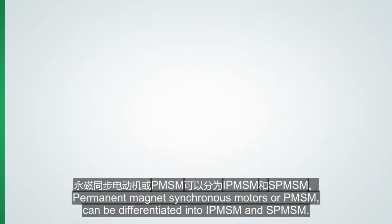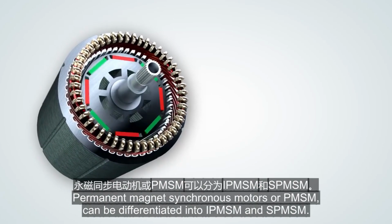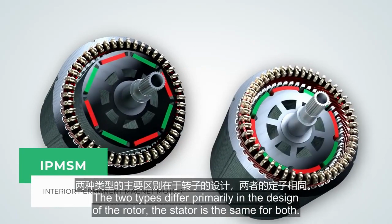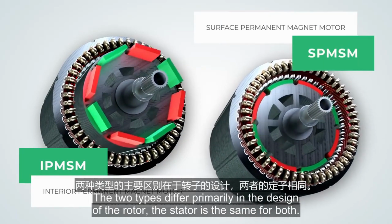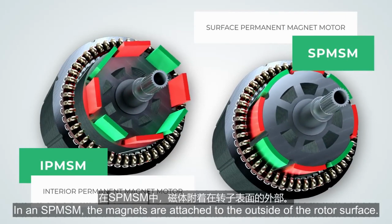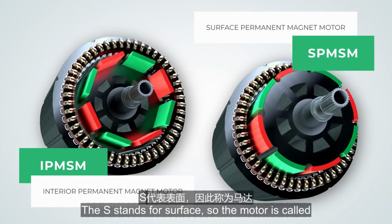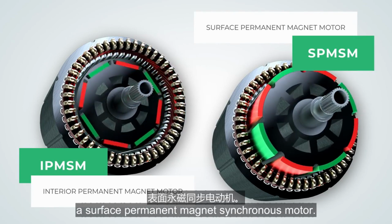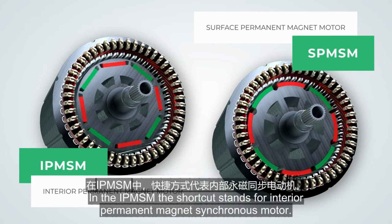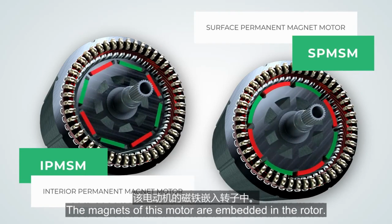Permanent magnet synchronous motors, or PMSM, can be differentiated into IPMSM and SPMSM. The two types differ primarily in the design of the rotor. The stator is the same for both. In an SPMSM, the magnets are attached to the outside of the rotor surface. The S stands for surface, so the motor is called a surface permanent magnet synchronous motor. In an IPMSM, the shortcut stands for interior permanent magnet synchronous motor. The magnets of this motor are embedded in the rotor.